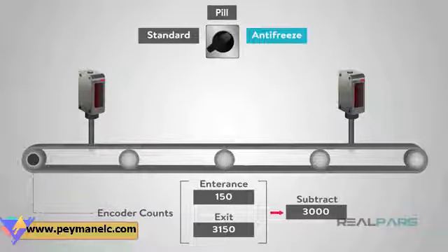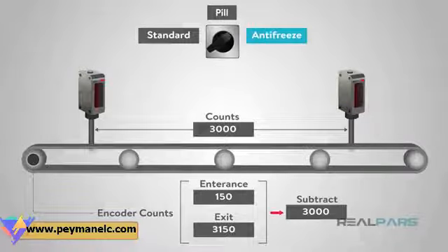You now know precisely how long it will take that bottle to move through the system, meeting the must enter and exit in a predetermined time frame, in this case, encoder counts. You have also made the flexibility aspect of different types of bottles, as well as being able to place the entrance and exit sensors any reasonable distance apart. When back in run mode, the code knows that there's a handle to ignore when it comes into the process, and doesn't fault the machine.